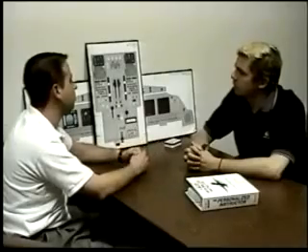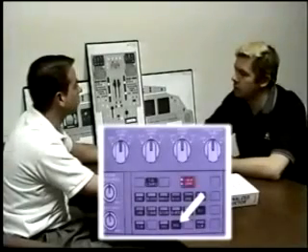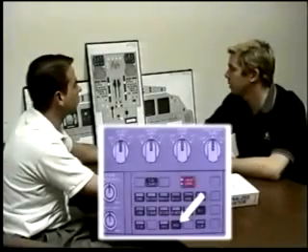Okay, so let's assume that we cancel a caution. Everything goes back to normal screen configuration. You pull out the status page, you see canceled caution and the title for the ECAM that you just canceled by selecting emergency cancel. You go, I really didn't want to do that. I want to run that ECAM. How could you bring that back? I'd press and hold recall, and that will clear all the canceled cautions and allow all cautions to then be alerted through the master caution system.